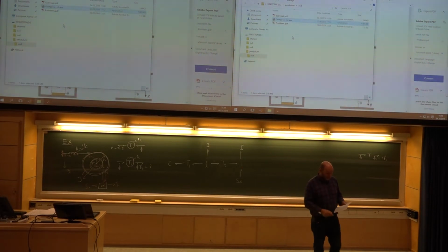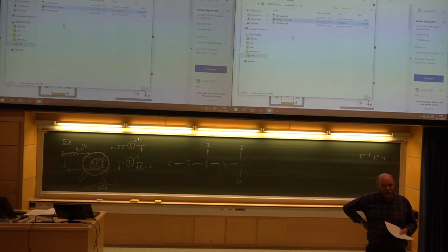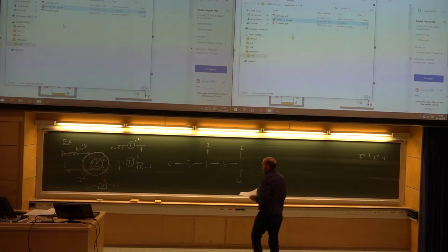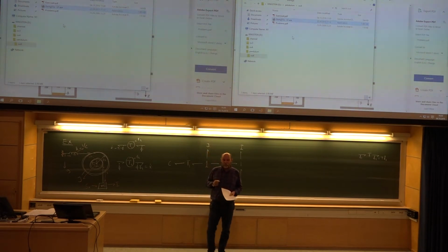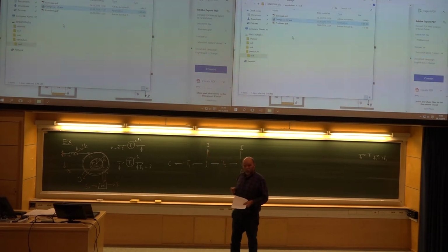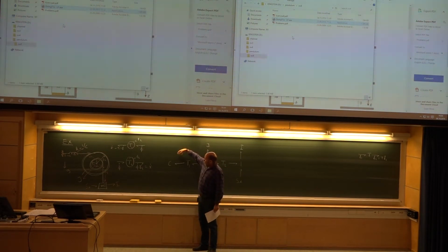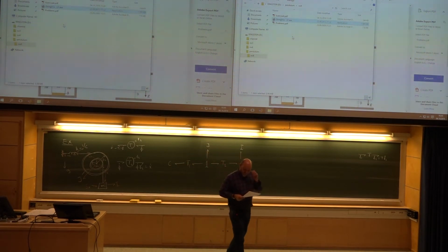So that should be the entire bond graph. And now we actually can do another simplification, if you can recall. Here we have a transformer and a spring. That's also part of these possible equivalences. Yes, we can have an equivalent C to cover both of these. Here I don't bother, I just leave it as it is.